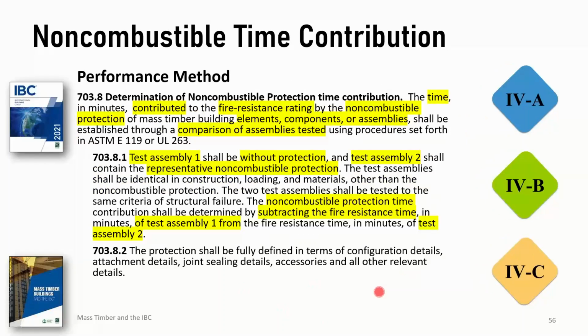Now I've been talking about, there's a lot of words here. I'll just tell you what this is about. This is showing you that you don't have to use gypsum wallboard for the non-combustible protection. You can use any non-combustible material, and if you have some other material you want to use, test it.